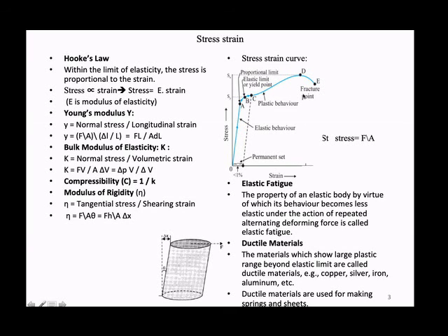See, we are dealing with stress and strain, not force and strain, because force depends on the area of the material we have chosen. It may be 1 mm, 2 mm, 3 mm, 4 mm diameter. But since stress is F by area, it takes care of all materials.